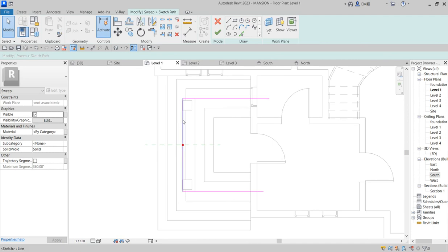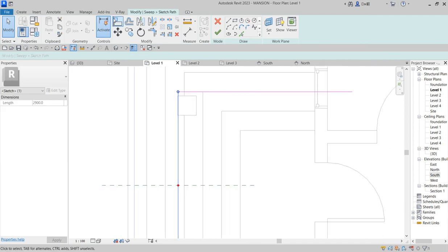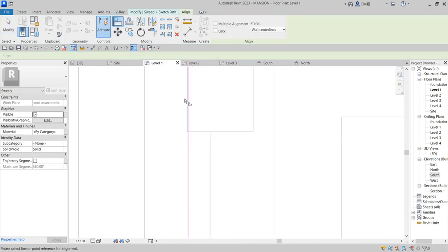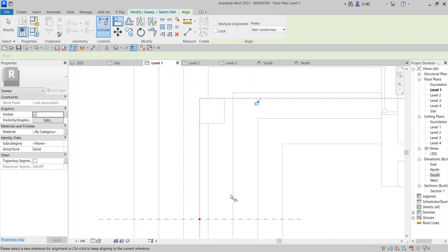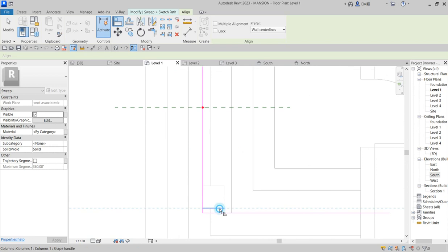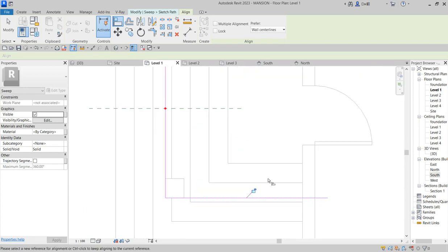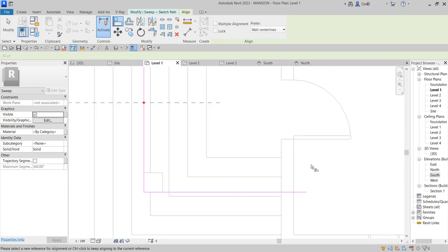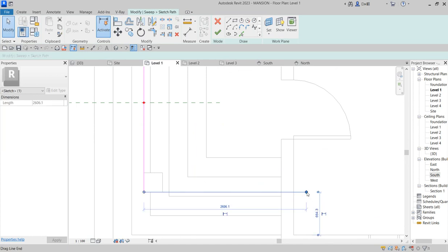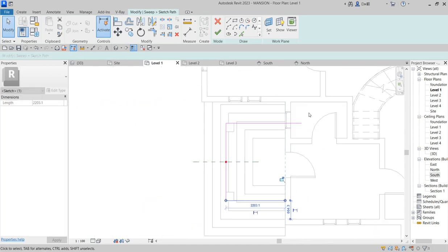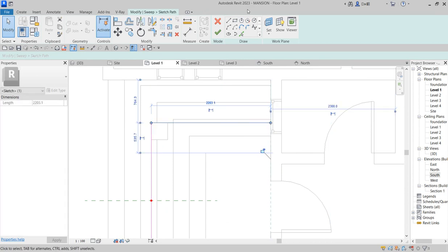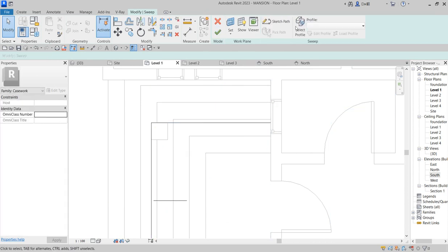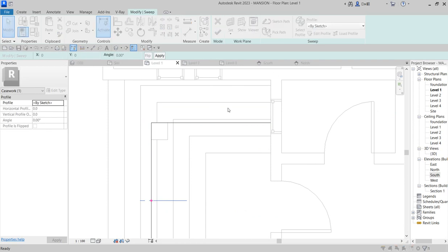So why this one is here, I align this one here, at the same time align this one here. Good. So I'm bringing this one inside because during the cutting section, I don't want to be seeing an error whatsoever. So as I've done that, I click finish, then I go to elevation.